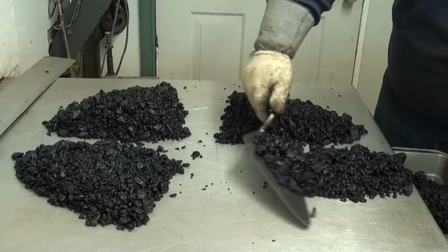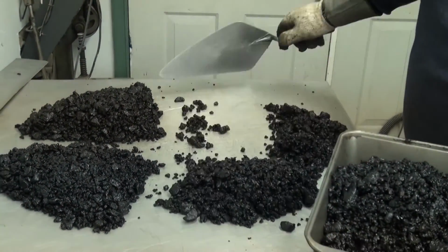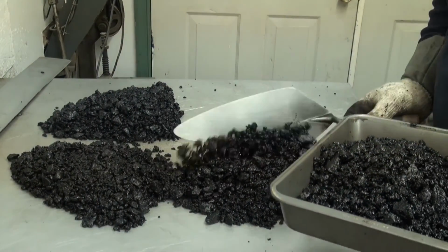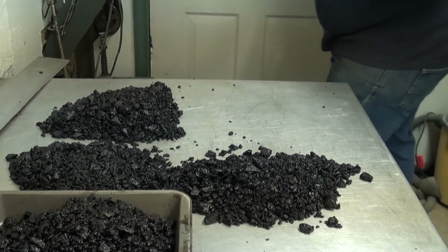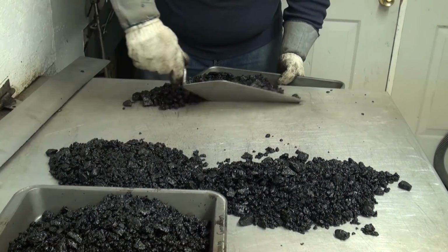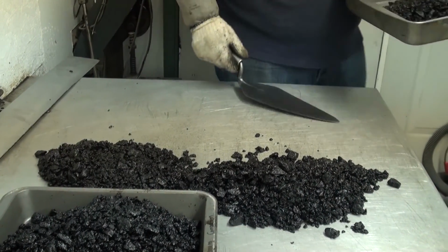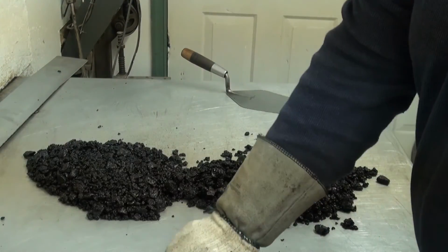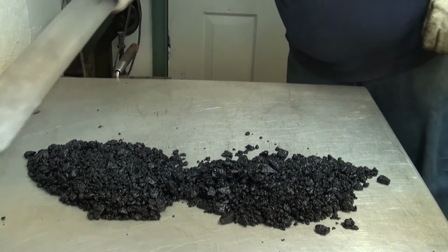Now that he's quartered it, he's going to take opposite quarters. Here we are, moving the other half over. Taking the diagonally cornered, opposite diagonal corner, put it in a pan. Notice this sample appears to be much larger than the surface mix we showed in the previous video. That's because it is. You need a little bit more material when you're dealing with larger aggregate sizes, and the sample requirement test sizes are bigger.